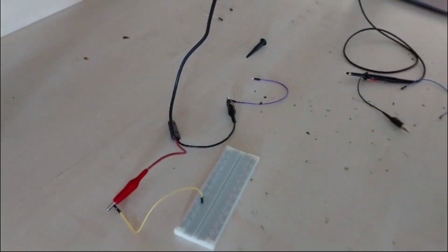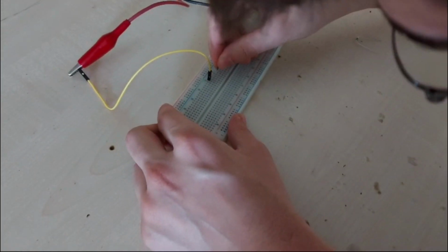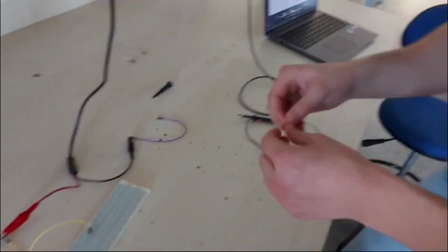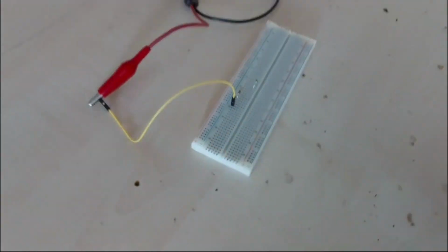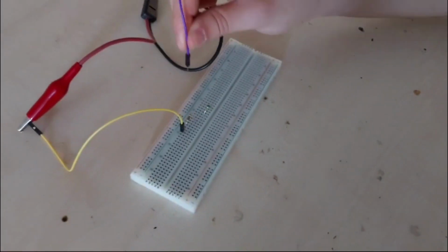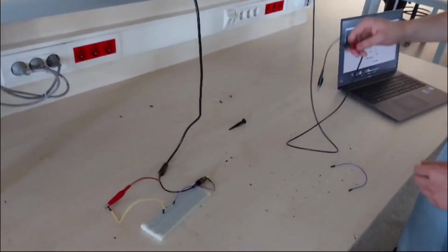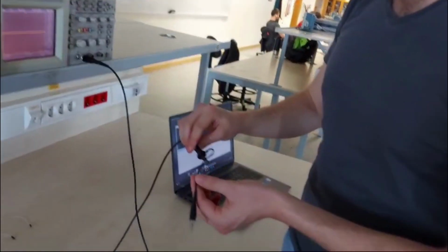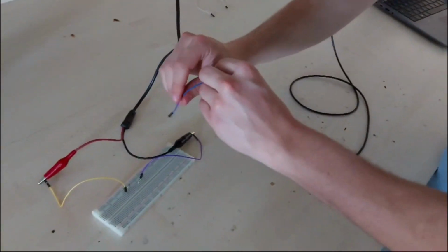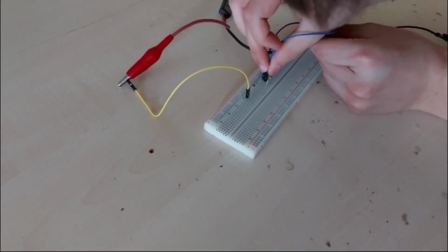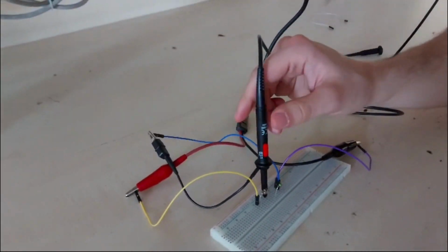First, I connected jumper cables to the power supply. I connected the hot wire, then the resistor with 100 ohms resistance, then the inductor, and the ground. To make the measurements, I connected the oscilloscope with its ground connected to the ground, and the probe to the other end of the inductor. This completed my circuit. I auto-tuned the oscilloscope to show me the voltage in correct amplitude.